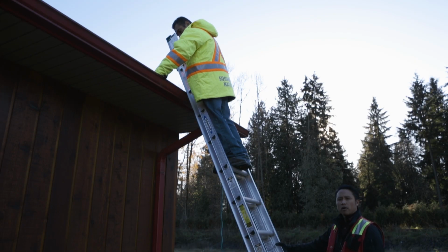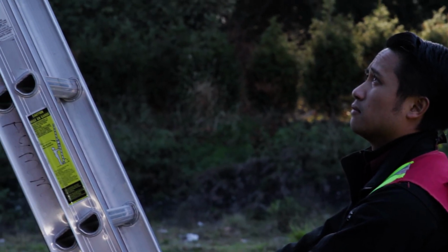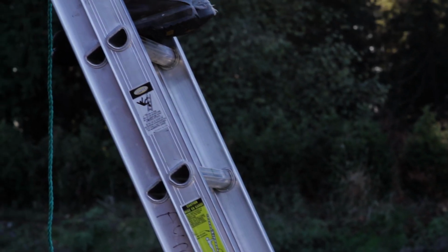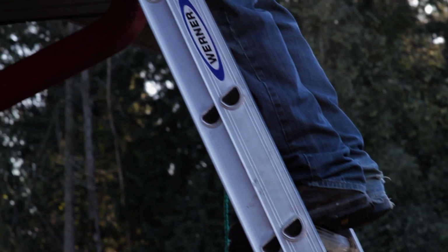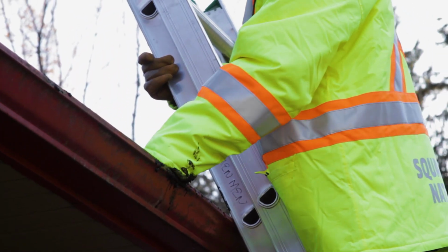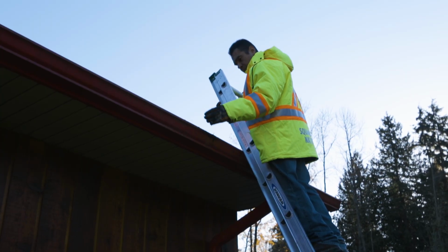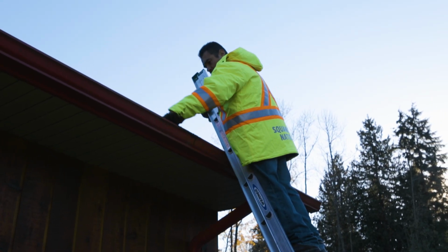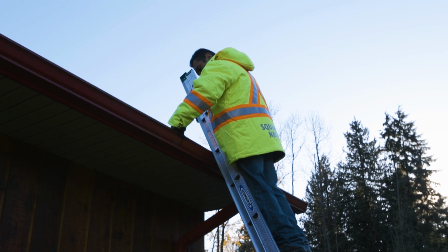Roofing is a very important part of the building envelope, and therefore roof maintenance should be a very important part of any long-term maintenance plan. One of the most important types of roof maintenance is to clear and clean all the organic debris in the gutters and in the drain pipes. If you don't do that, the water can build up and start to infiltrate into your building envelope assembly.